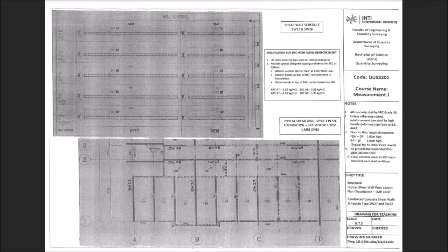It's 3.9, so you take note that the formwork has different category if the height is more than 3.9. Okay, this one is mentioned in the SMM under formwork. And then we also have the clause mentioned about BRC if the height is more than 3.5 meter. Okay, so it will influence the way you measure for BRC and formwork. Even if you deduct the slab, you still get 3,700. So 3,700 is still more than 3.5 meter.